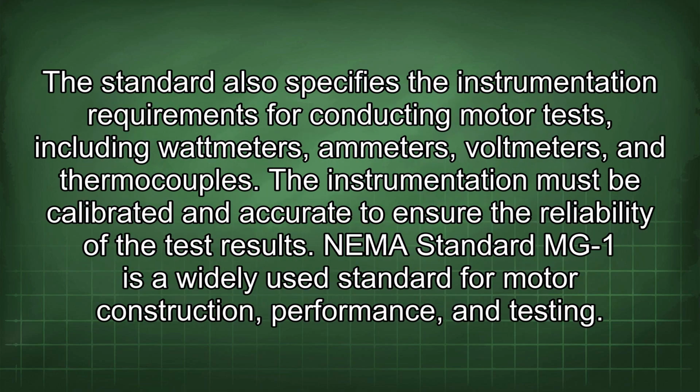The standard also specifies the instrumentation requirements for conducting motor tests, including wattmeters, ammeters, voltmeters, and thermocouples. The instrumentation must be calibrated and accurate to ensure the reliability of the test results. NEMA Standard MG-1 is a widely used standard for motor construction, performance, and testing.